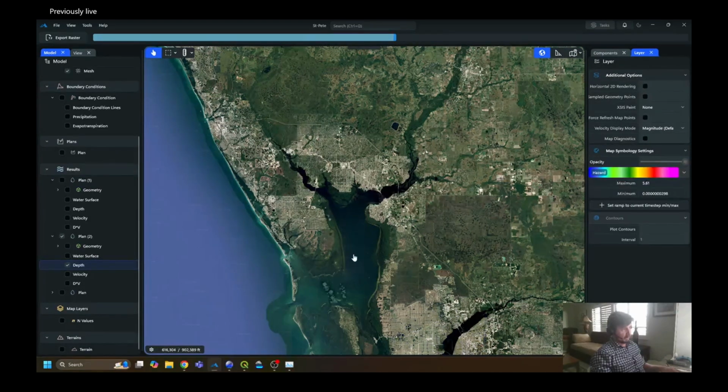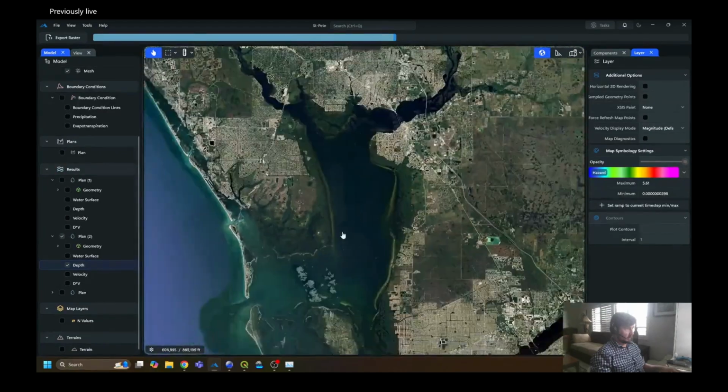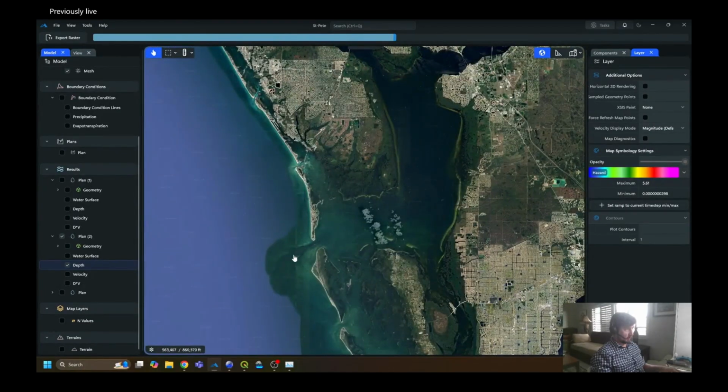There's a whole wind dynamic going on here that this model is not taking into account. But I can create a proxy for it by creating a boundary condition. So if I know that it's going to move directly through here, I'm getting a lot more of a direct push this way. So maybe if I'm most interested in this region, I'll put the boundary condition more direct. So it's now shooting it this way, as opposed to if I want it to be shooting in water from this direction, then I have to play around with the topography. I'll put the boundary here on a perpendicular line.